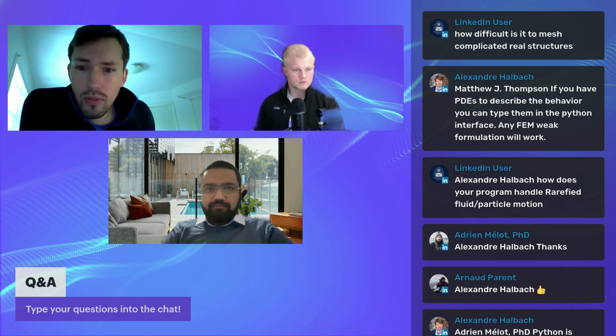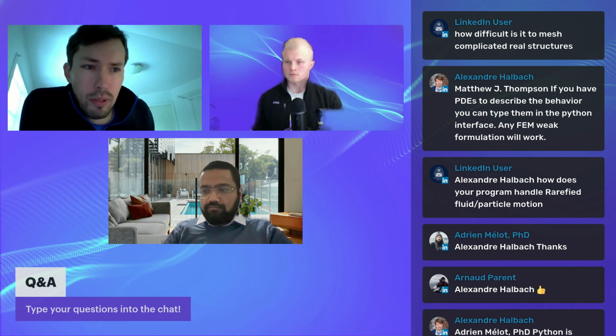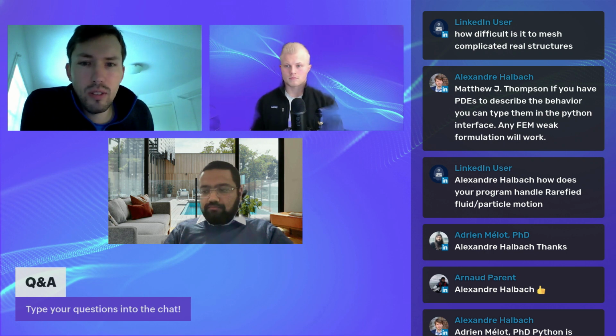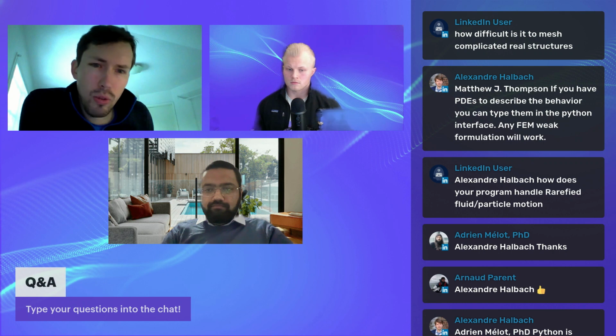Regarding MEMS devices where you have thin layers, this can be a really tough time if you have a lot of thin layers and you have to transition between two different meshes across different layers. We have a specifically made tool for that, which basically collapses all the layers to a shared footprint, meshes that in 2D and extrudes from there, which makes it basically the best possible quality mesh because it's extruded across all layers and it just works in all cases. And you don't end up with weirdly shaped tetrahedra because the software tries to match two layers across a few hundreds of nanometers. So these two cases are covered. So I would say it's not that difficult.